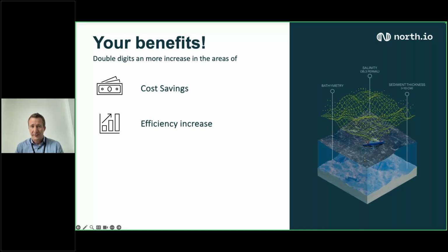Quality enhancements. Since we can read raw data, we can very quickly assess the quality of raw data and see if it's feasible. Hydrographic data is complex, and errors are made; errors are human, they are also made in acquiring data. With our technology, you can very quickly get an understanding of whether the quality is met that we want to achieve, that we maybe also contractually agreed on.